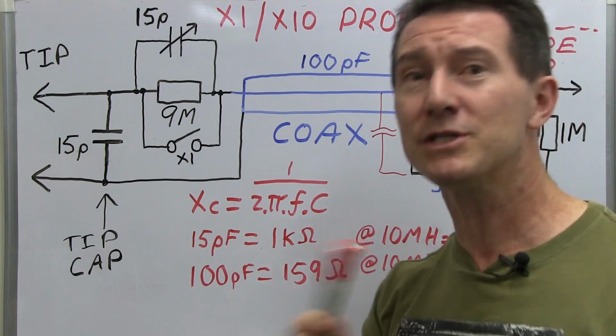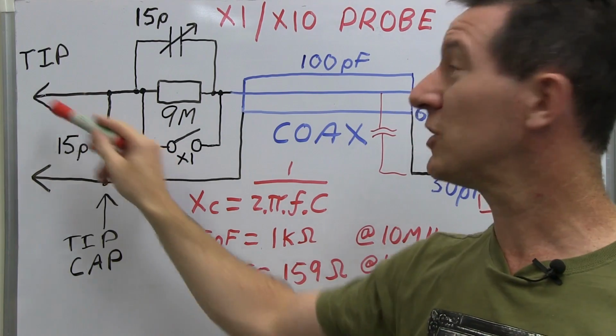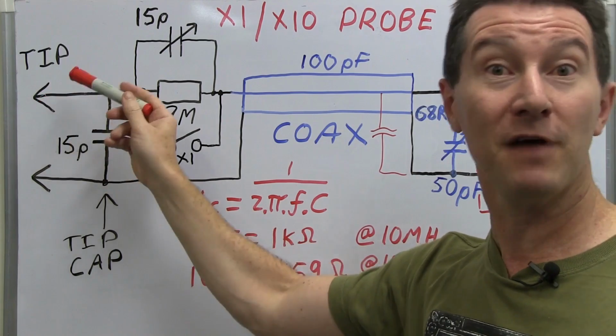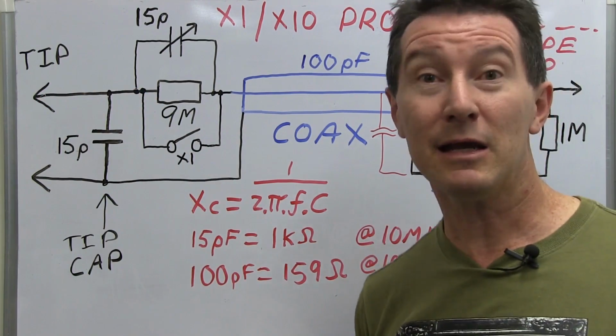Incredibly low input, but still, let's say you've got no loading effects on your circuit, you're driving it with a low impedance load, then your signal should go faithfully directly from the input through to the scope without any attenuation.